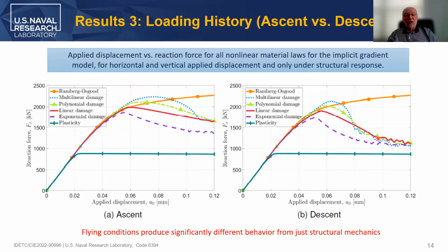First, we did it without the multiphysics, so this is just the mechanics, which essentially means that the ascending and descending variations come from the boundary conditions on the temperature, and the humidity, on the temperature only, because here we don't have humidity, being the ones that are applicable. So again, you see that here we start getting significantly different results when it comes to the softening and the damage between the two cases.